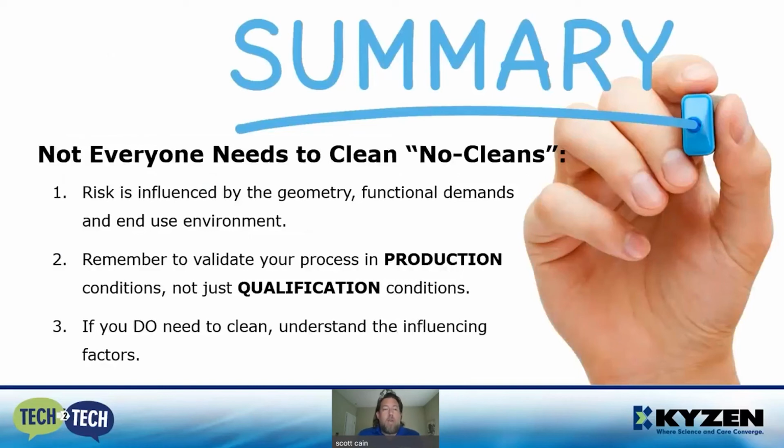So in summary, not everyone needs to clean their no cleans. That's influenced by things like the geometry, the functional demands, and what that end use environment is. One of the things that we see that sometimes causes problems is people will spend all this time dialing everything in, from their reflow to their cleaning process, for the qualification portion, and then they'll let it stray a little bit once it gets to production.